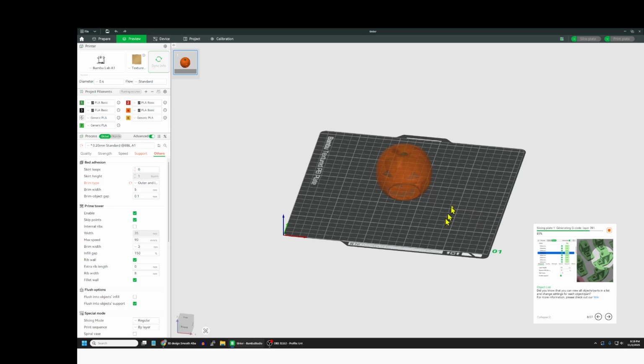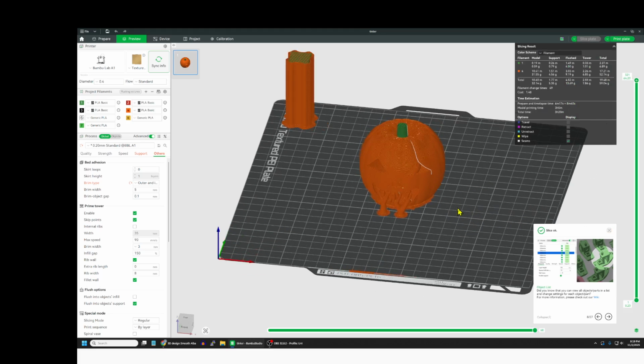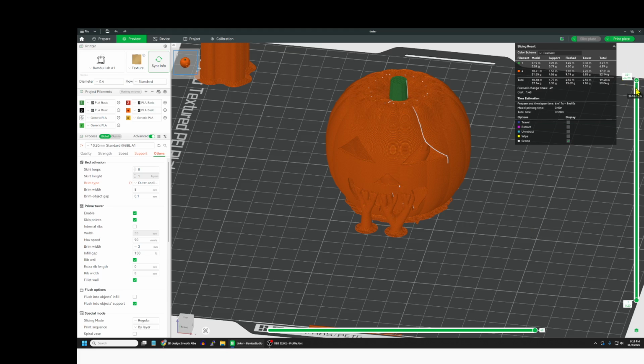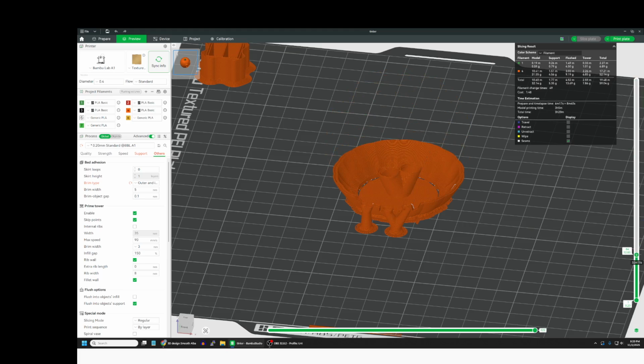And we'll take a look at it after it's sliced. So let's make it big, okay? And look at all the support. I'm going to take it down, okay, all the way down to the bottom. On the bottom level, you can see right here, this is the 38 millimeter piece we put in there, 0.4 millimeters high, to give the tree something to build on. I had trouble, things broke off, so here's our tree going up, okay? We have the main tree right here, and we have these two pieces right here, more trees. As it goes up, it branches out.